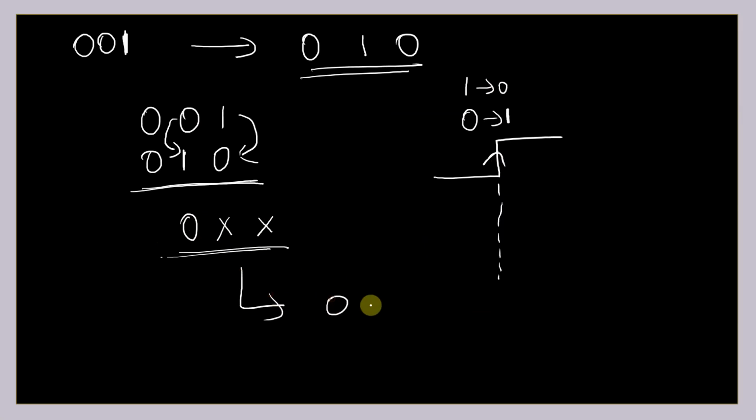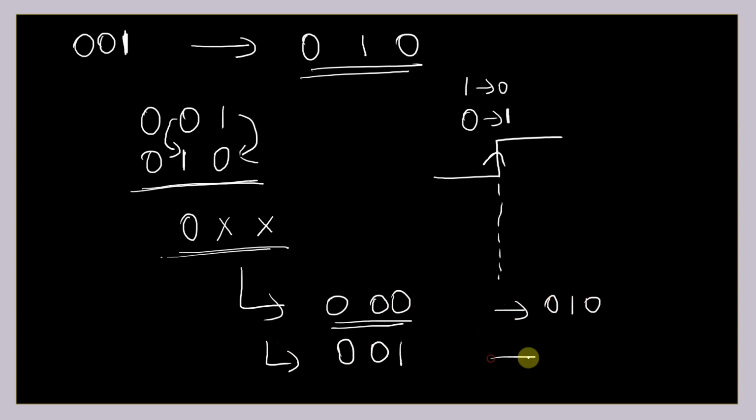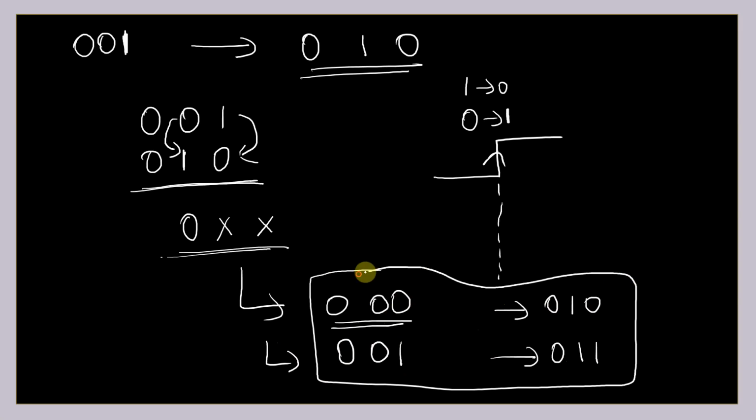Let's say the values they settle to might be 00, or 01, or 10, or 11. See how much ambiguity is present over here. So the read pointer can be any of these values, because they have entered into metastable state, they can be any values after getting stable, right?